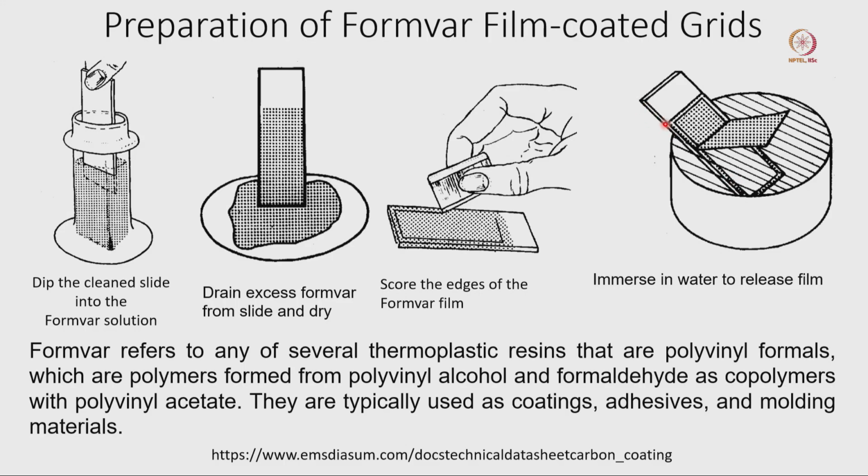When you immerse it at a 45 degree angle, this particular part is already detached from the glass slide, and when you gradually dip this one, this plastic will start floating on top of the water. If you go slowly, you should not be in a rush. Hold the glass slide using a tweezer tip and do it gradually, very slowly. You should immerse this glass slide, and this plastic will start floating, and then gradually you go all the way